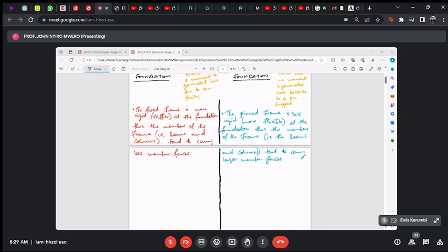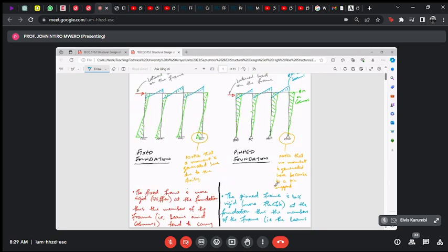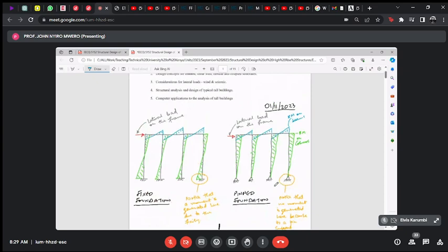So that's definitely an advantage to the fixed foundation for the column. If we fix the column at the foundation, we have slightly lighter member forces up at the top. How much lighter is also a big variable, depending on the size of the building, how many floors and things like that.